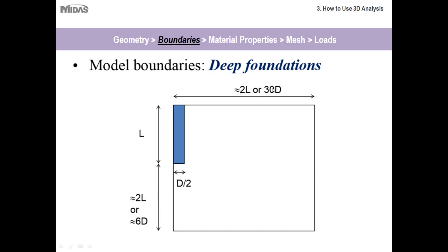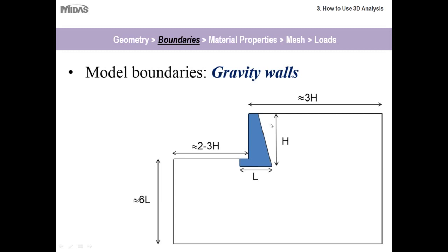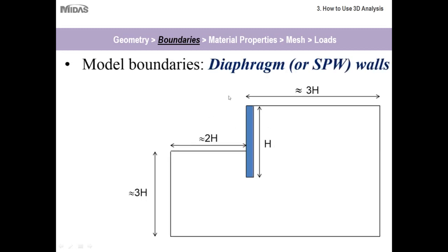These are very conservative, so you can do them a little smaller if that works for you. But just keep in mind that your boundaries should be far enough away from your stresses and your strains, so that you have everything modeled and everything included. So what I'll do is I'll give you all a copy of this PowerPoint at the end of this session, and then also we'll post the recording, so that when you start doing your own numerical modeling, you'll have these just as a reference.